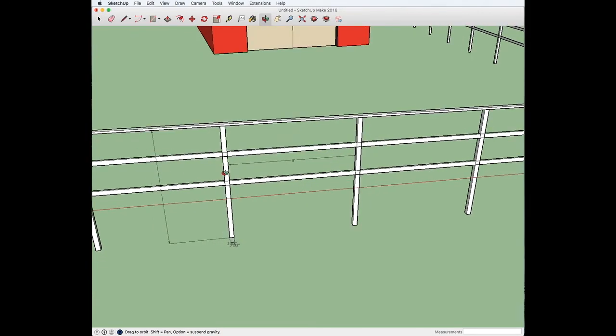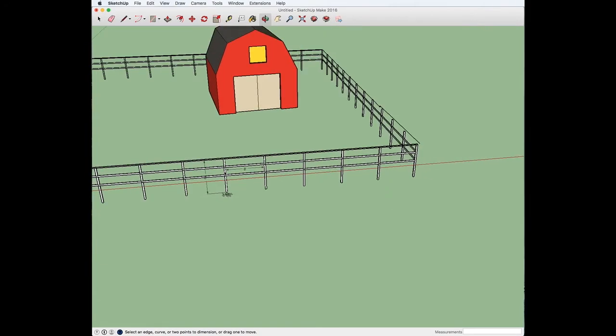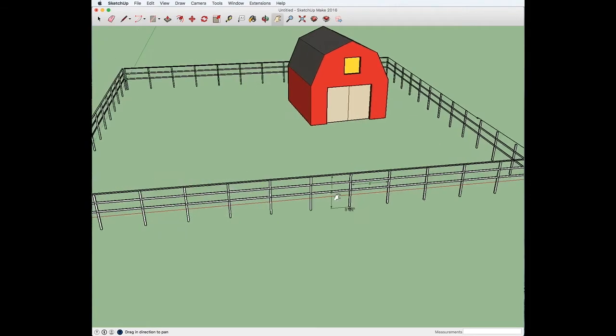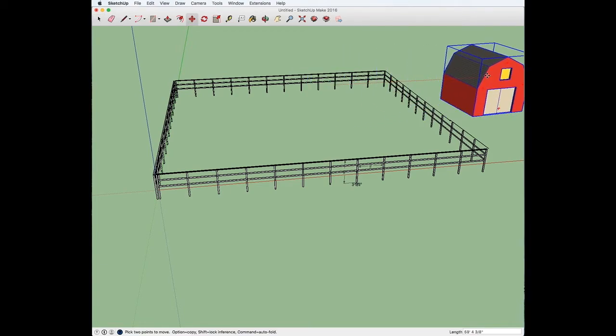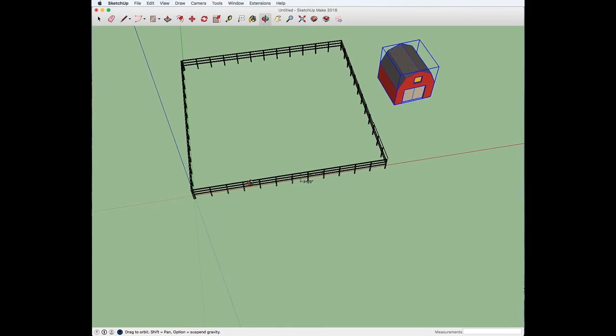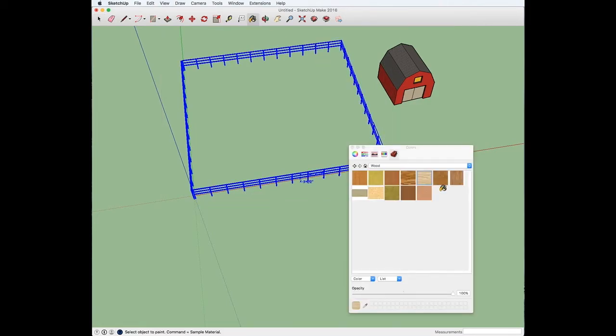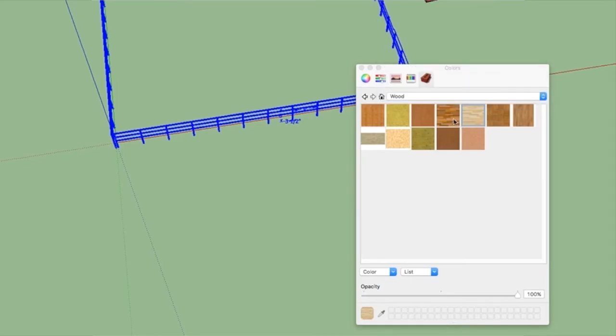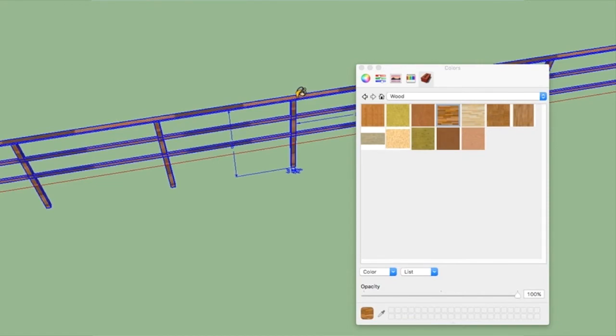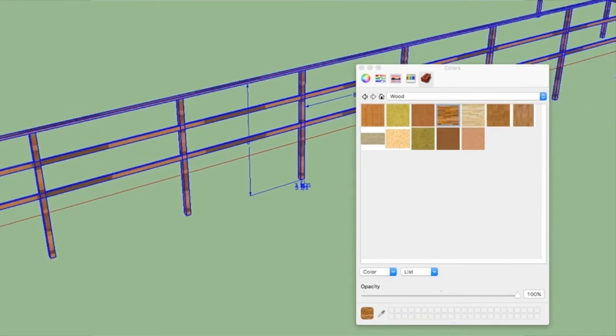And another thing you can do is test things out. I want to paint this a certain color. What's it going to look like if I paint it a barn red color, for example? So I'm going to move this out of the way for a second just to streamline this. We'll go to the top, and click this little arrow tool, which allows us to select multiple things. Then if we press the paint tool, we can say, let's say we want to leave it as a wood color. You click it, and now the whole thing is that wood color.